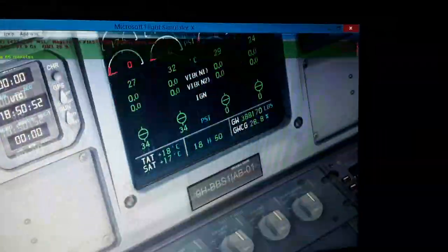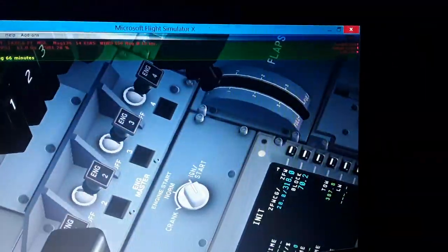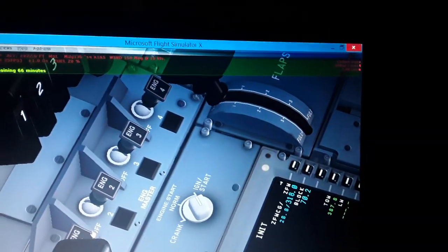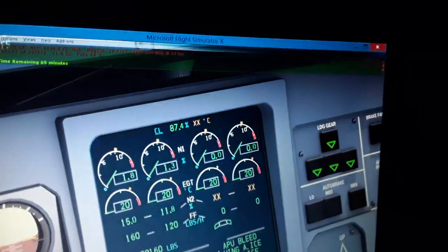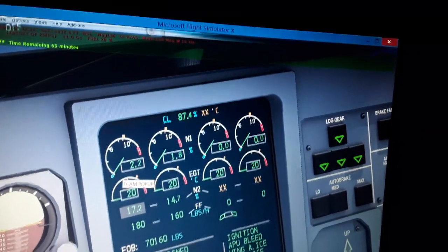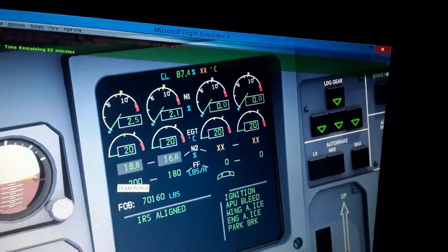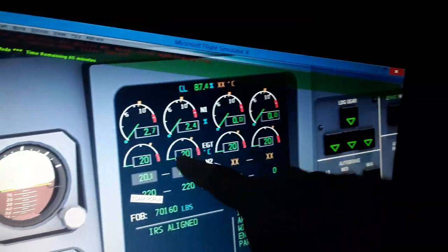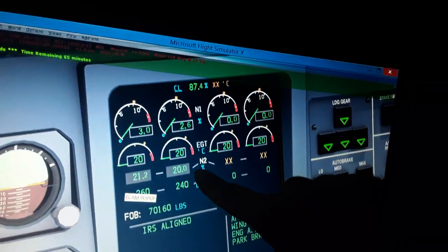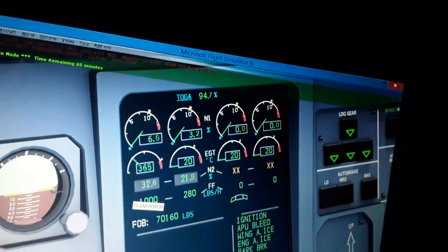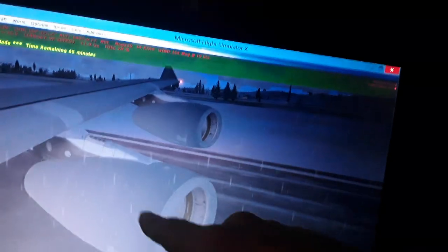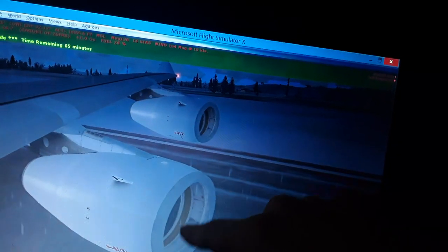It's gonna open the engine start valve of the engine to pressurize the engine. So I'm gonna turn the engine 1 and engine 2 master switches, which is gonna start the pressurization. The engine and the fuel flow valves are gonna turn on when the N2 reaches about 20%, 24%. Here we have it. You can see the engine start here.